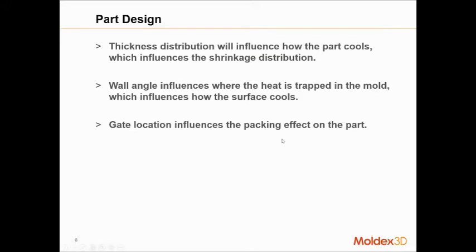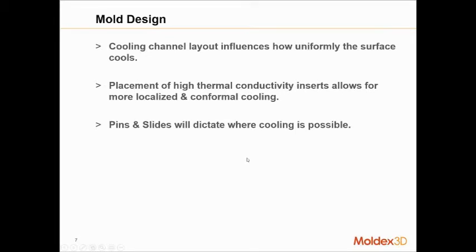So the gate location will always influence the packing effect ultimately, which, as we'll explore in a few moments, will also influence the volumetric shrinkage. And if we have a difference in volumetric shrinkage, again, that's where the warpage will come from.